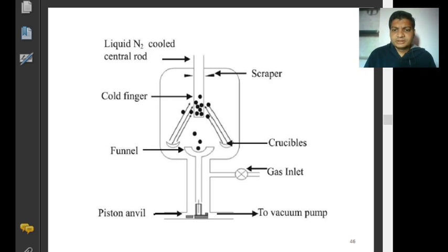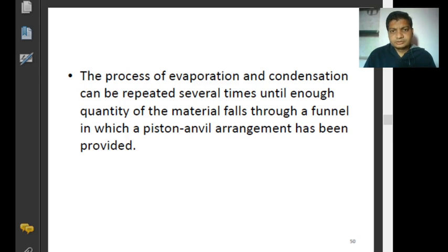This is a very good method to obtain nanoparticles of a size less than 100 nanometer. The evaporated material size, as we have seen, is more than 5 nanometer, but after condensation the size might increase from 10 nanometers to 100 nanometers. We can control the size by controlling the pressure, and then we can make oxides of these metal nanoparticles. So these are some of the advantages of this method.